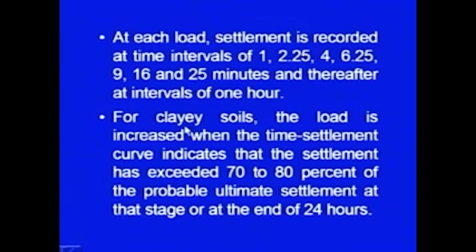So, we will be taking the next incremental loading when the time settlement curve indicates, we will keep on monitoring the time settlement curve and we will increase the loading when the settlement has exceeded the 70 to 80% of the probable settlement at that stage. Or if it is taking too much time, more than 24 hours, then after 24 hours we will take the next step of incremental loading.